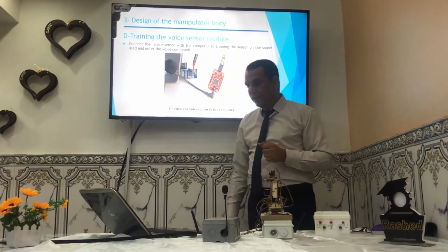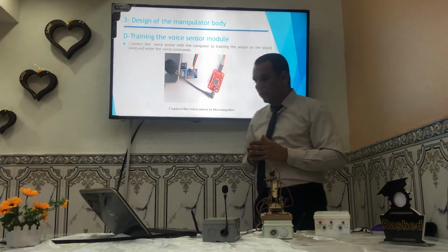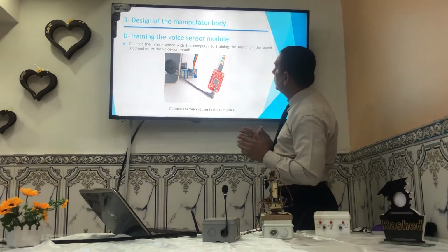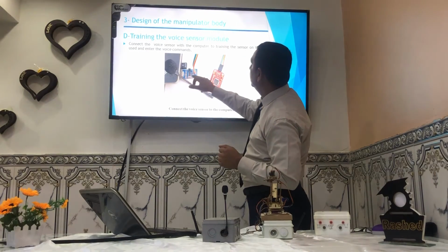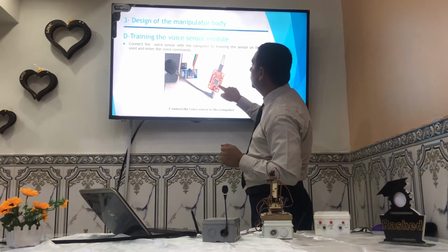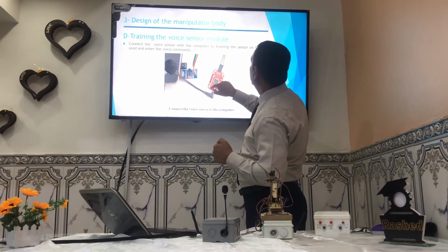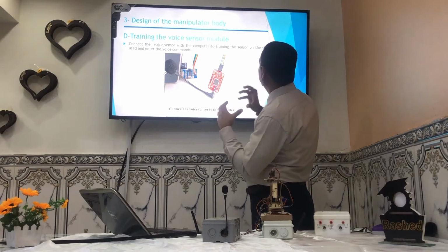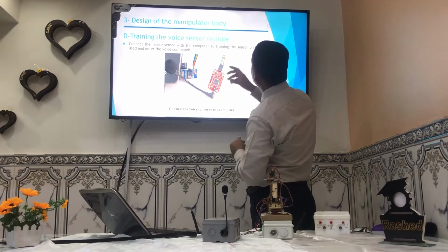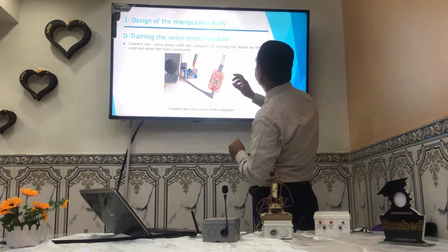Next slide, training the voice sensor module. Now, connect the voice sensor to the laptop through small chips to train the voice sensor module, with the Arduino Uno library for connection and programming, to check and train each voice command.